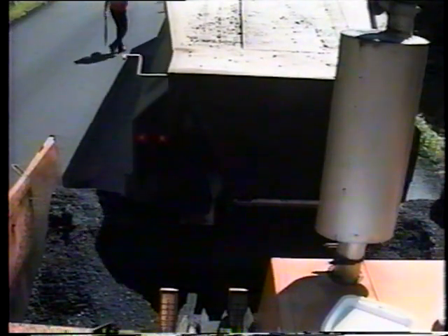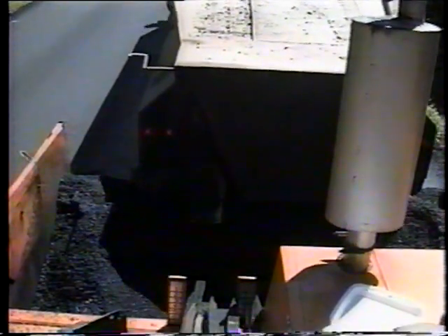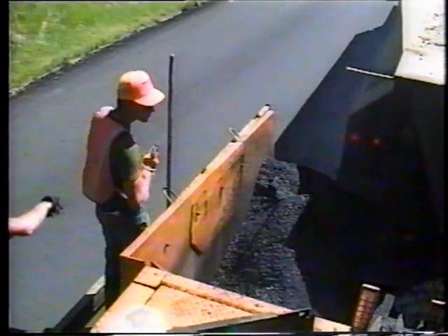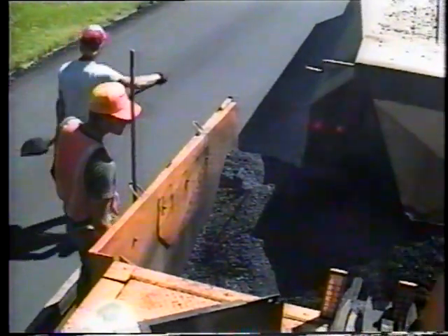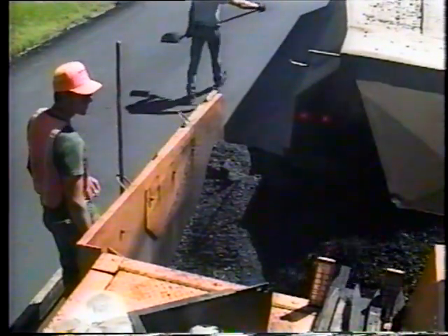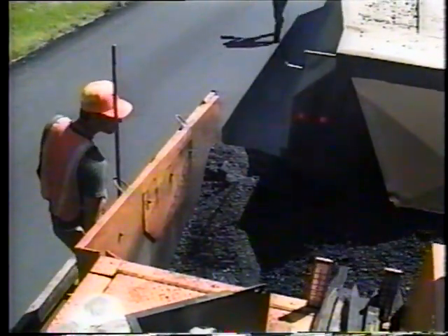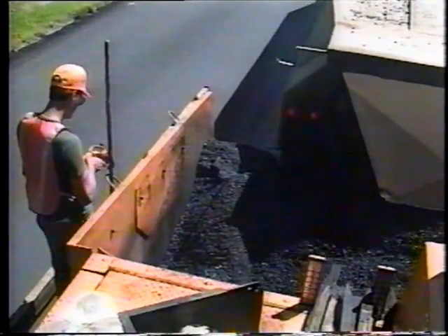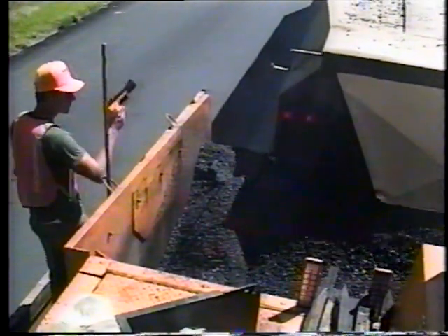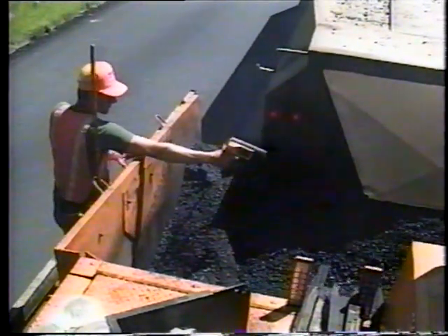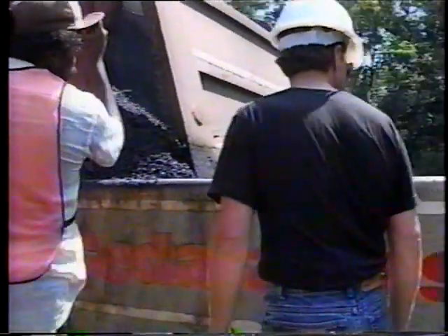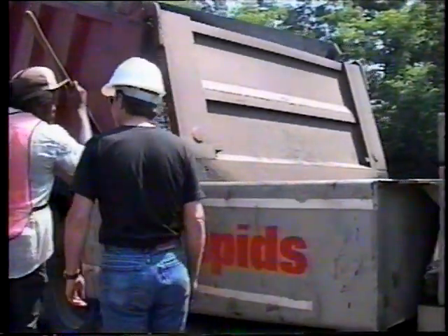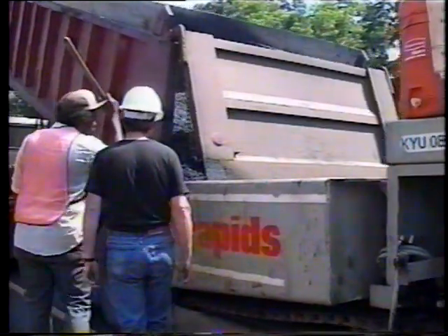You should also visually inspect the mix. You can tell a lot by its appearance. Some problems will require that adjustments be made in the batching or hauling of the mix. Some problems may be serious enough to outright reject the whole truckload. Later in Part 3, we'll look at some examples of defective mix to help you recognize such problems. In any case, tell the plant inspector, the contractor, and your supervisor immediately if something doesn't look right.